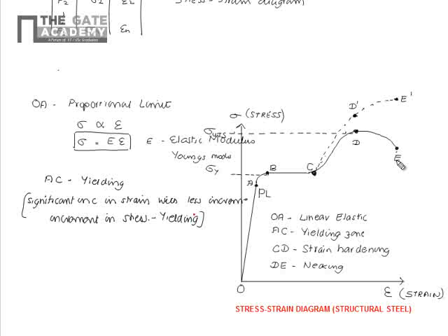Now in this above example we have calculated the stress sigma based on the formula P by A, but A was nothing but the original cross-sectional area. Similarly, strain we have calculated as change in length by the original length, where L0 is the initial or original length.